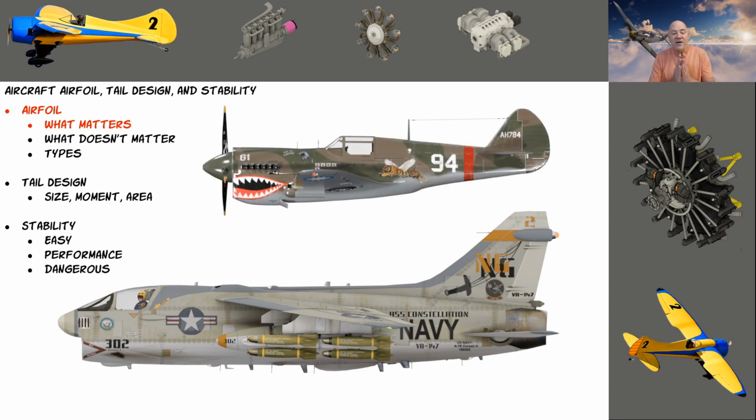So when we think about the airfoil, I have learned that it just doesn't matter that much, okay? If you've got either a semi-symmetrical or a flat bottom wing, which is like a Clark Y, and we'll dive into airfoils, on model aircraft, because of their size and their cube wing loading and what we're doing with them, it doesn't matter that much. In full-scale aircraft, the airfoil is to get the absolute best amount of lift for the most efficiency through the air. And we don't care about that with model aircraft that much.